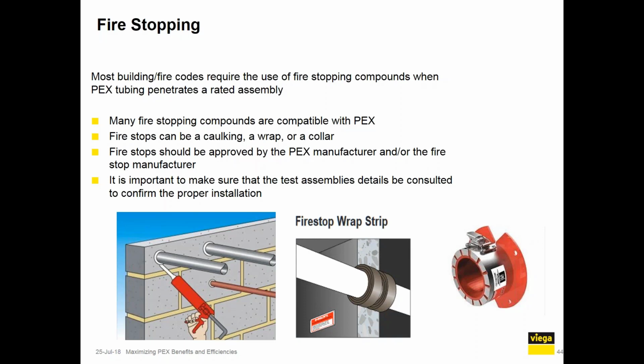The fire stop should be approved by the PEX manufacturer and/or the fire stop manufacturer. So it's important to make sure that these are compatible with each other and that you're consulting with test assemblies to make sure you're doing it the proper way with installation.